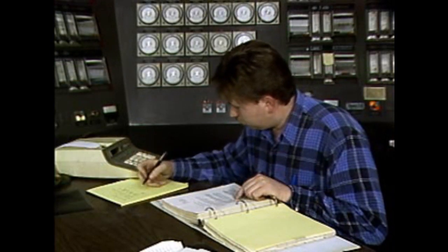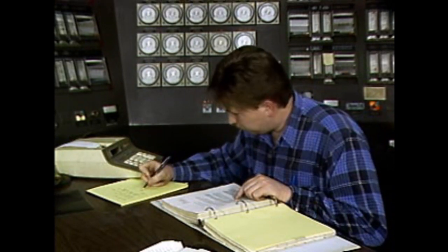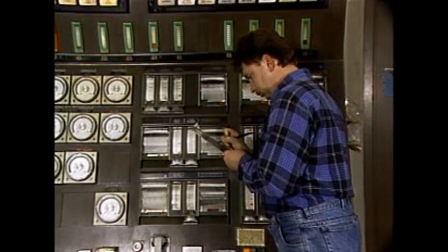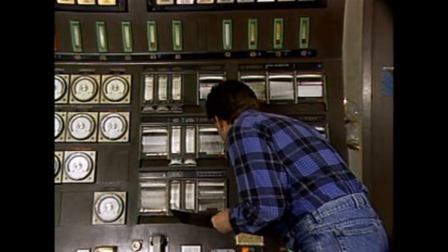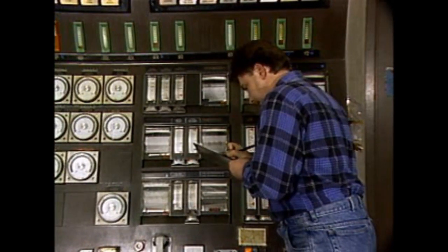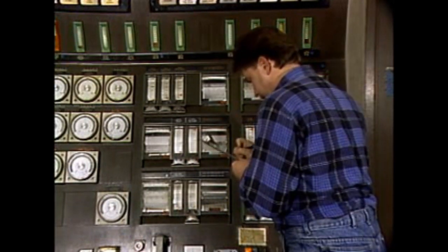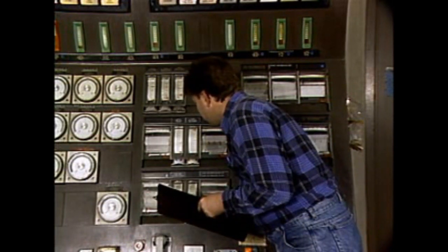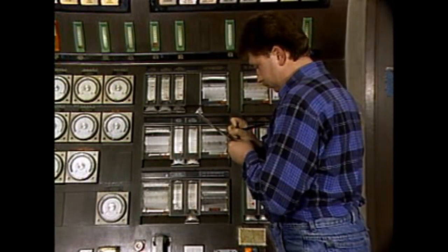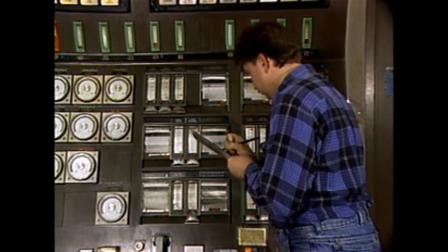Now the operator has an idea of the amount of time he has to work with as he continues to analyze the trend. He checks the inlet temperature of the product that's being cooled by the cooling water system and finds that it has also increased. This would account for the increase in the cooling water temperature. The high product temperature indicates that there is a problem with the production process that will need to be corrected. But in the meantime, the cooling water system must continue to cool the product.